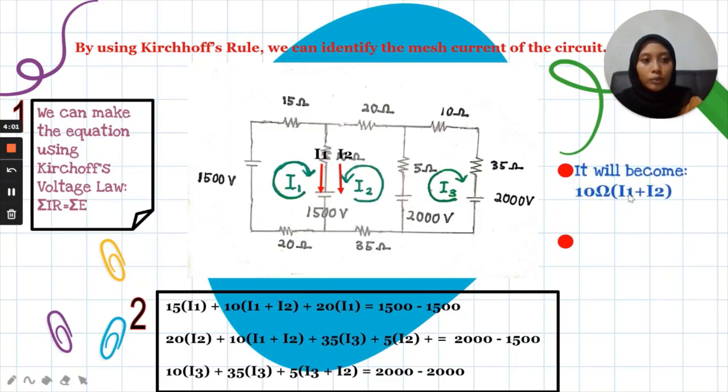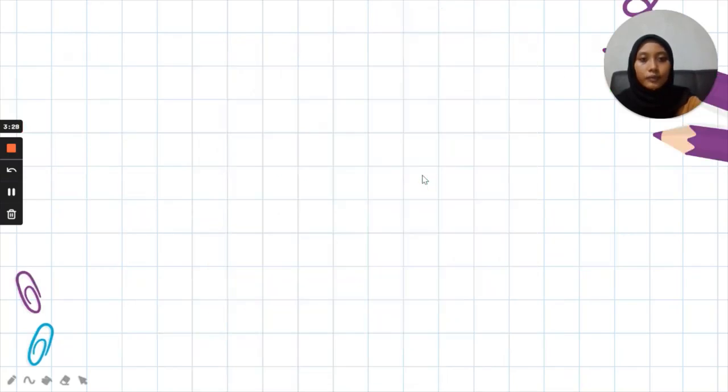It will become 10 ohm times (I1 plus I2) plus 20 I1 equals 1500 minus 1500. Why is it minus? Because we need to consider the loop direction and also the direction the circuit current flows. It goes the same for this 5 ohm resistance.